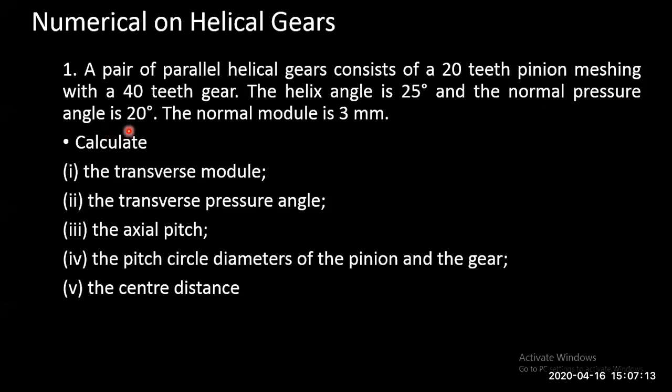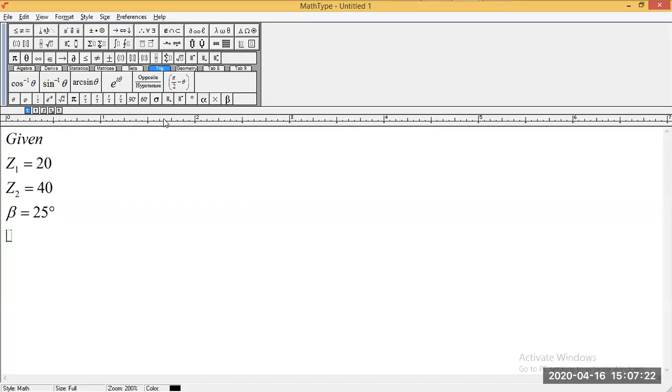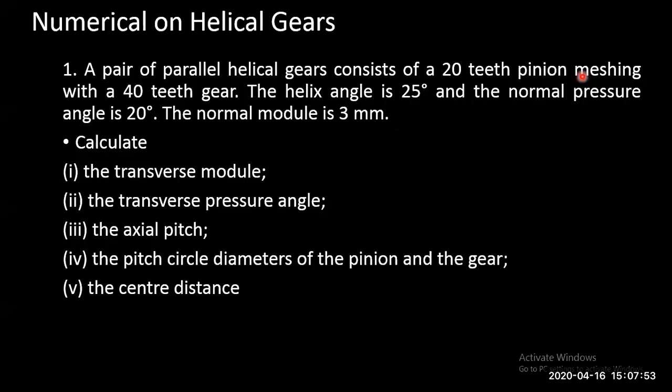So this is the form of teeth. You can see that it is 20 degrees. So this is alpha. Don't confuse between the helix angle and the normal pressure angle. So 20, 20, 14 and a half, these are the form of teeth. Any other than these angles, if it is given, then you need to use the form. There is a normal pressure angle.